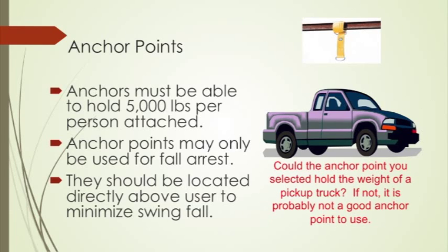Electrical wiring, piping, and other support systems are not good anchor points. It is important for employees to consider how their selected anchor points will affect their free fall distance. OSHA regulations do allow companies to engineer their own anchor points, provided they meet the OSHA requirements.